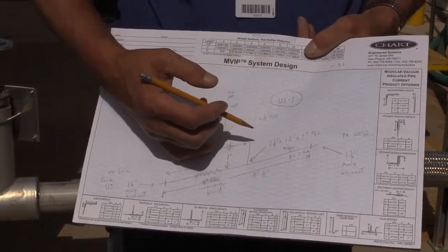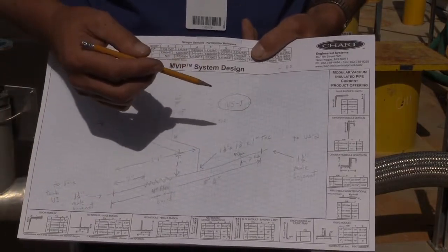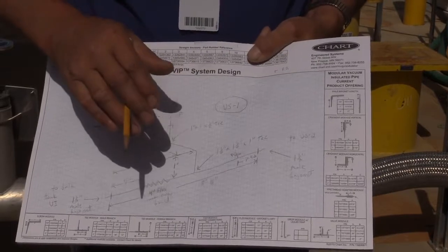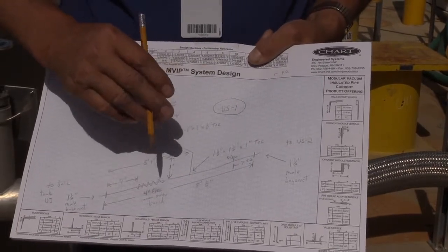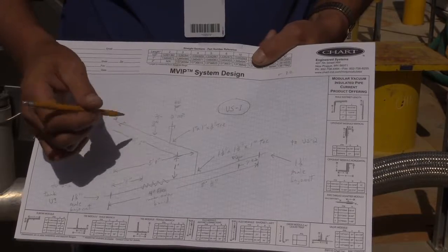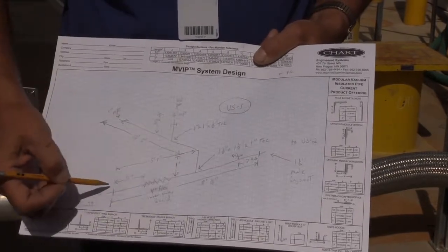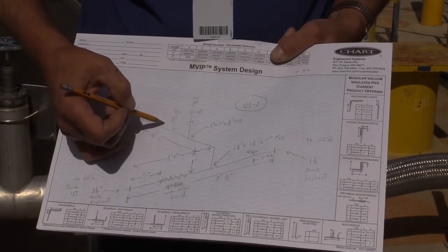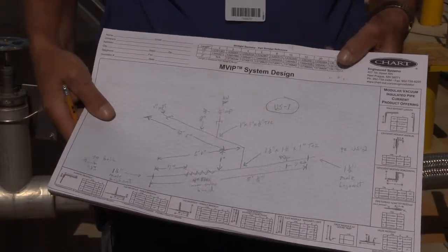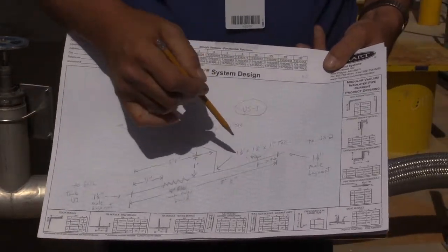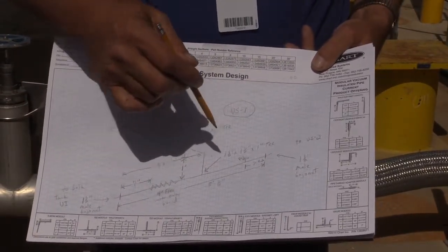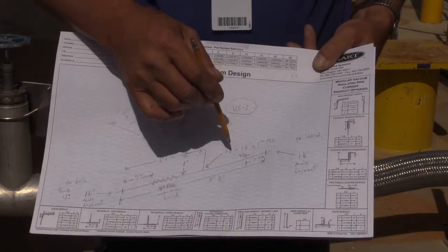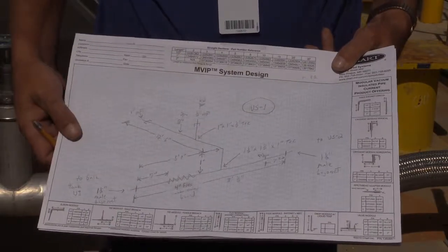This can be very critical in areas where it needs to go through walls, or if there are obstructions where the pipe is very tight to something, that the pump out needs to be in a specific spot. In other words, this pump out could be anywhere on this entire section. It could be here, it could be put in here, it could be put virtually anywhere, but again, it needs to be labeled on the drawing, so when the draftsman draws this up, they understand that that is a critical point of where that pump out needs to be.